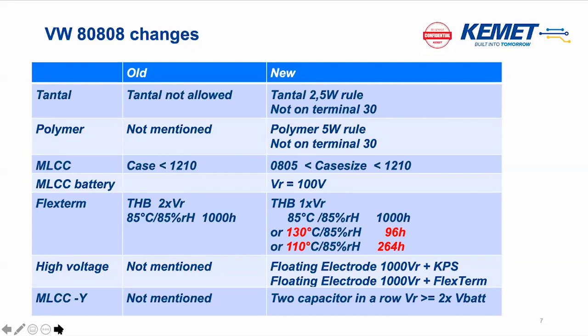Polymer capacitors, we try to avoid the word tantalum a little bit because it has a bad reputation, even though the tantalum was not the guilty part. What's not mentioned, so there was a lot of uncertainty about how I can use this technology, which definitely gives you some improvements. Since 2015 we visited Volkswagen, and now we get that in the specification, explicitly mentioned: tantalum polymer. And they have a 5-watt rule compared to the 2.5 watt for tantalum with MnO2.